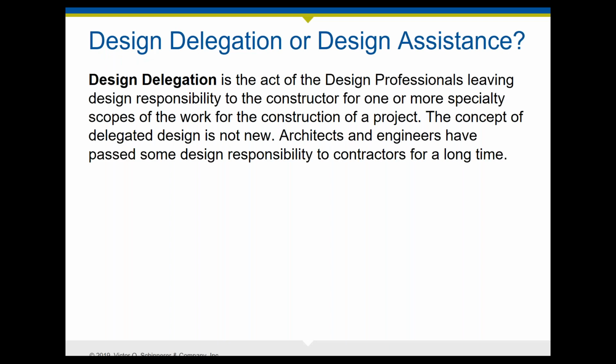Okay, design delegation or design assist. Design delegation means that the design professional really assigns design responsibility to the contractor. It's an assignment of responsibility under a certain performance criteria, and it's usually for the design of a discrete portion of a construction project.